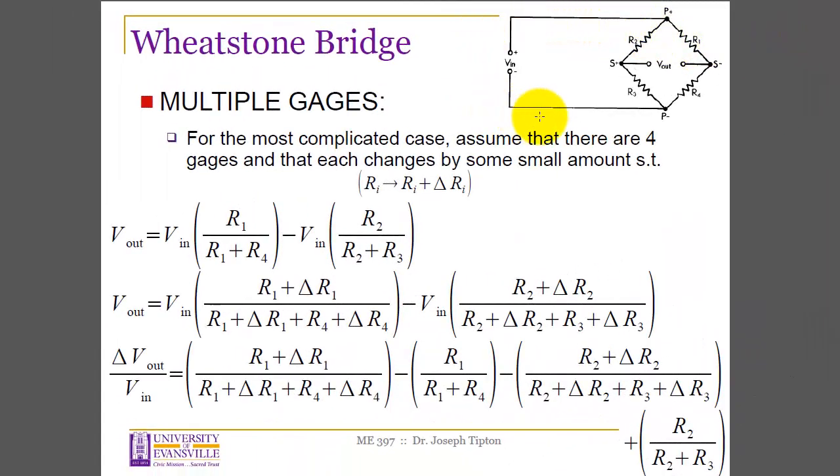Let's focus right up here at this image of a Wheatstone bridge first. And let's recall last week where we derived the relationship between voltage and resistance for the Wheatstone bridge. Remember that we have to use the Wheatstone bridge because a strain gauge would experience a resistance change on the order of maybe a few thousandths of an ohm, or 10,000ths even rather.